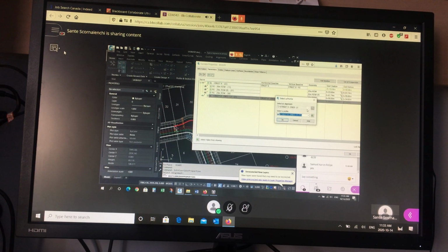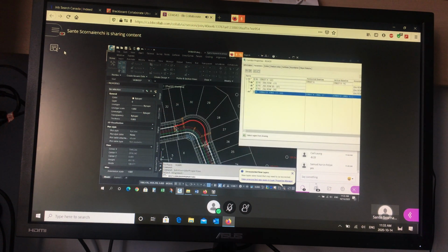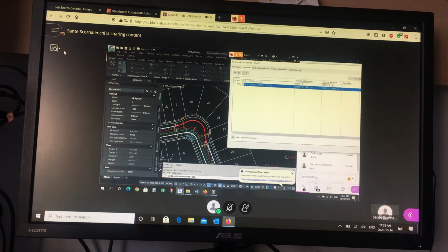And there's usually two, right? There's the surface, existing ground, and then there's the proposed one. This is red dashed. This is a green one. So that's the one we want, the design profile. Say okay. So now I have a baseline, and notice you'll see the highlights here. I'm going to collapse this. So there's the main road center line, and the model also includes the horizontal alignment of the gutter. Now notice you can expand to see the regions of the main baseline.